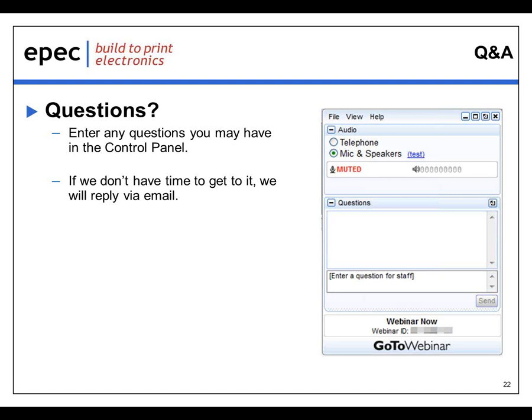In some cases, the boards have been around for a while. They've been designed with out-of-date design strategies, and we can use more current design strategies in order to generate more cost-effective solutions. We can take a board that was designed with a single-track technology between pads. Using the newer technologies that are much more commonly and widely used, we can go to 2-track or even 3-track per channel routing and clearly drive layers out that way.